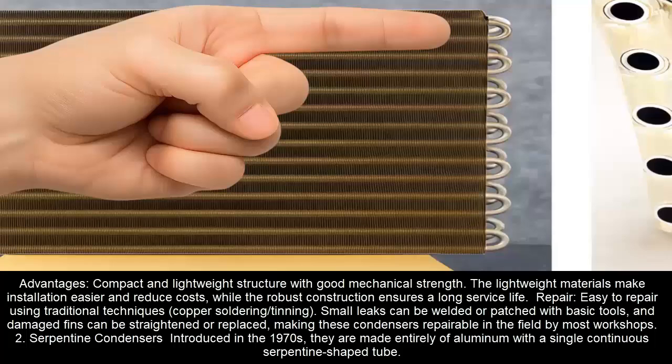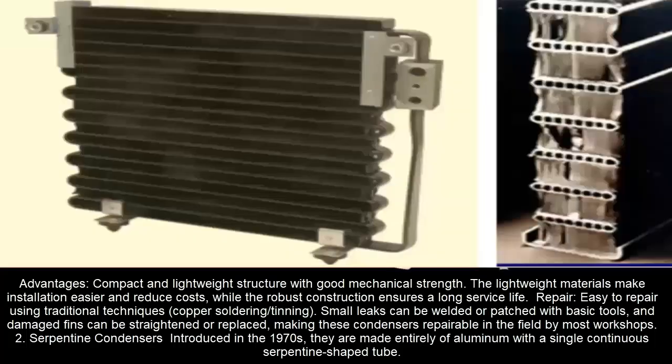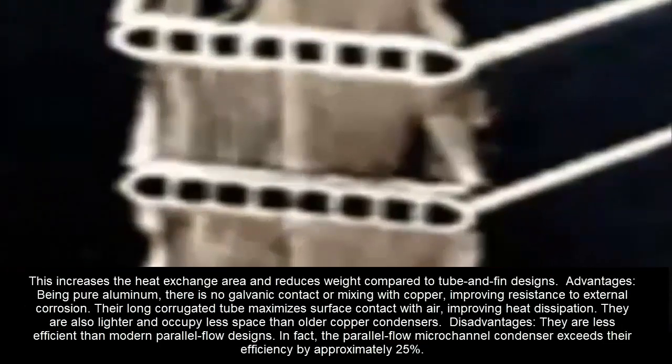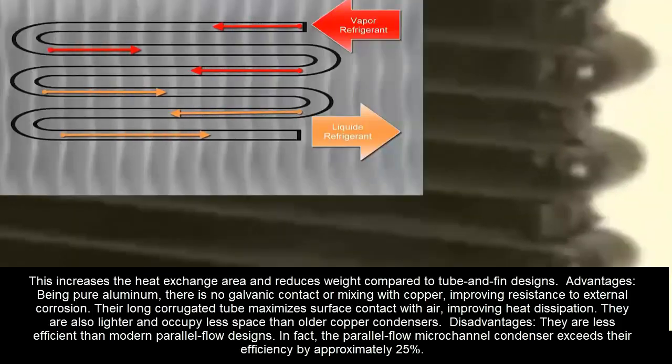2. Serpentine condensers. Introduced in the 1970s, they are made entirely of aluminum with a single continuous serpentine-shaped tube. This increases the heat exchange area and reduces weight compared to tube and fin designs. Advantages: being pure aluminum, there is no galvanic contact or mixing with copper, improving resistance to external corrosion.